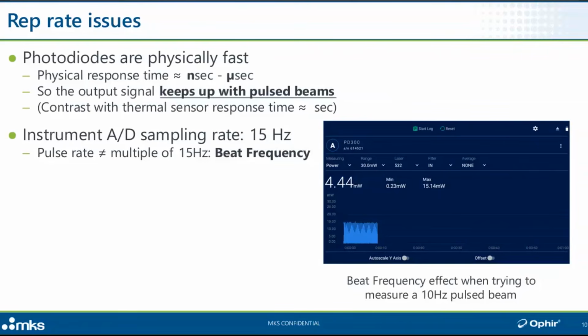Typically what happens in a laser power meter is you've got the sensor, whether it's photodiode or something else, and it sends out a raw analog electrical current, as we said, that's proportional to the power being measured. And then you've got the meter, the display, the console. Every manufacturer uses a different word. You get the idea. Might be a handheld meter, desktop, whatever. And the first thing that analog current meets when it comes up to the meter is the front end, the A to D sampling at the entrance point into the meter, the analog part of the meter.